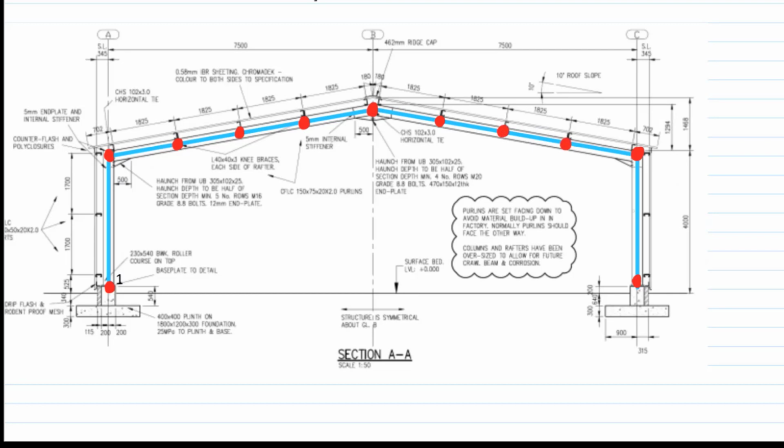And then we could also add where the girts are on the side to apply loads there. But for now, to keep the model simple, I'm only going to add purlins on top. If you wanted to, you could have 3 very closely spaced nodes at the top to account for the apex and then the purlin each side. So that would be in this vicinity, but I'm going to just have a single node at the top.